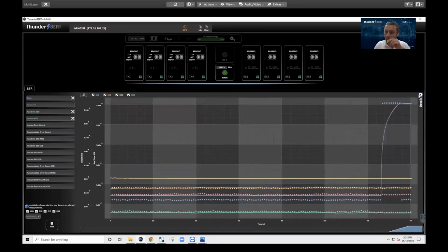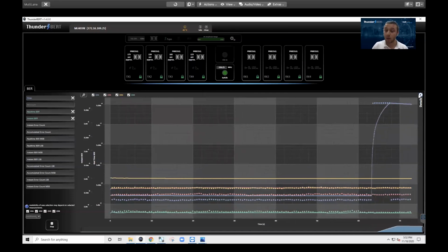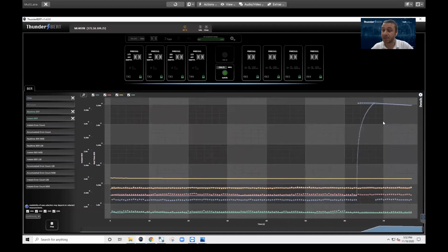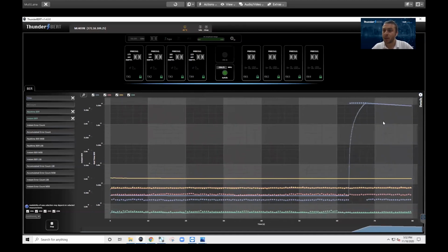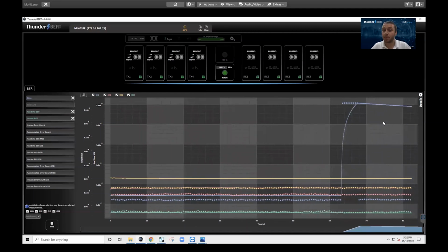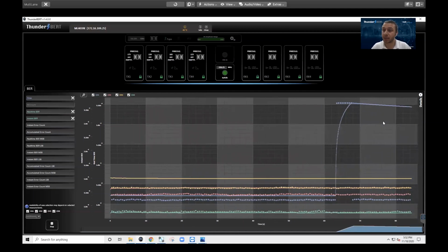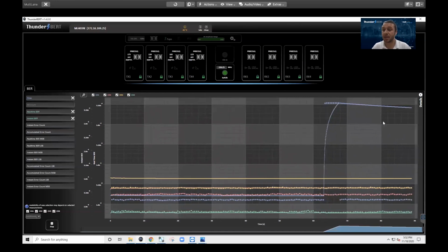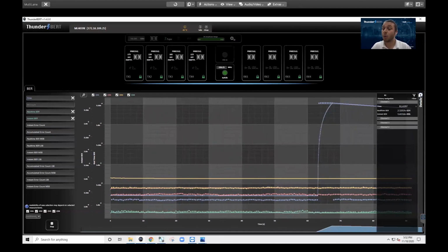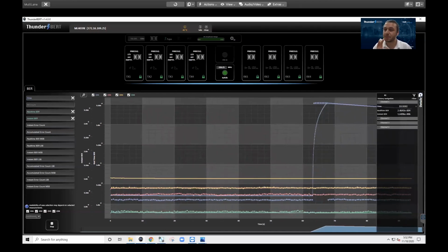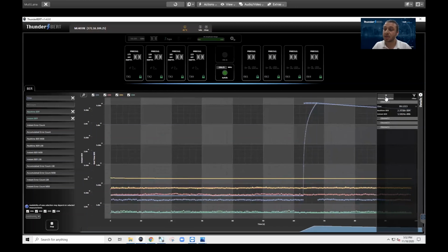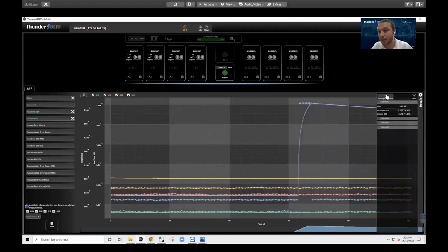And now you can see, if I hide the details tab for a second, that channel 1 now shows a huge jump in the real-time and instant BER. That is representative of an error burst, which could potentially break your link in the field. So you need to be extra careful to identify and get to the bottom of those error bursts. Now, what we do to give you full visibility into the error profile of your device under test is a feature we call history navigation. I enabled history navigation in the details tab here.